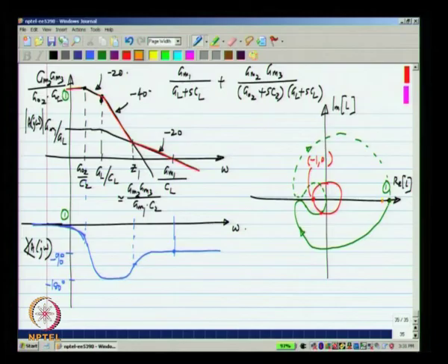Let us say it perhaps started from elsewhere, and again this goes close to the negative real axis, it comes back like that, and then finally it goes to the origin, that is for sure, and the mirror image of that will do that. Again there is no encirclement, but you see that the Nyquist plot enters the unit circle at an angle very close to minus 180 degrees.